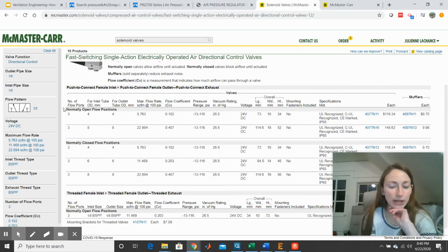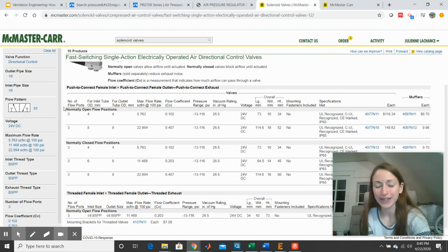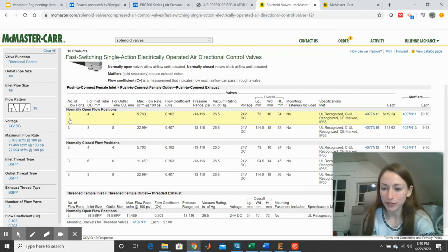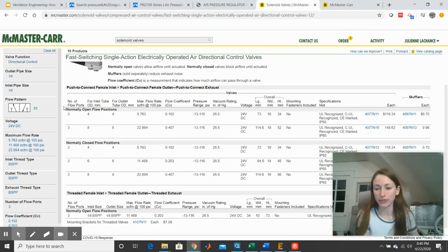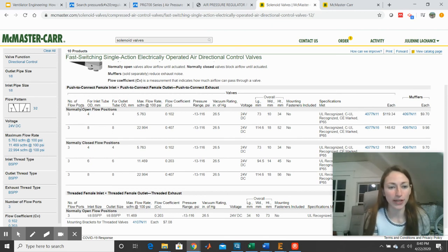So if I have a valve that's very close to the mouth of my patient, I may want it to fail open in the event of some mechanical failure so that the patient can attempt to breathe normally if they're still physically able to breathe. So be very mindful of this when you're designing the safety components of your device. You may want it to fail open. So I'm going to design for that. I'm going to have mine normally fail open.